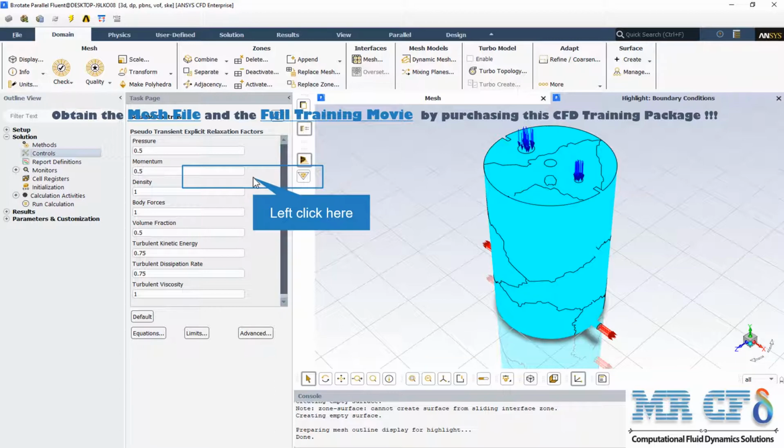Typically, an increase in the under relaxation factors brings about a slight increase in the residuals, but these increases usually disappear as the solution progresses. If the residuals jump by a few orders of magnitude, you should consider halting the calculation and returning to the last good data file saved.